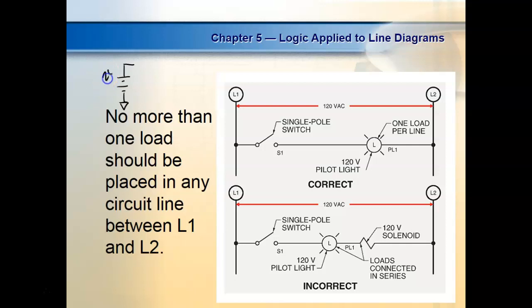And let's say I start off with 20 volts. And then I'm going to come out here and put a 1K resistor. And we'll call it R1. What would be the power dissipated by the R1 resistor? Get out your calculator, get out your pencil, calculate that for me. Now, of course, here the easiest formula would be V squared over R. This is 1K. So you can do the current and everything, but you get the same answer.